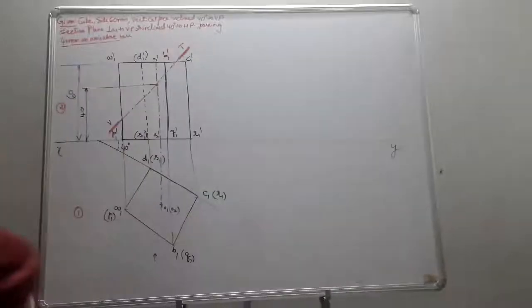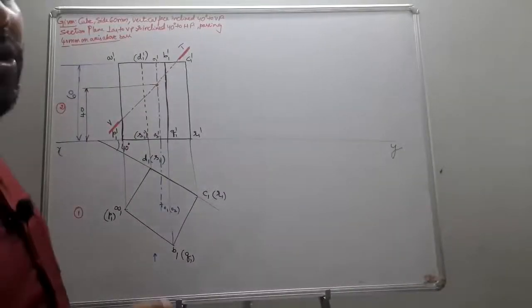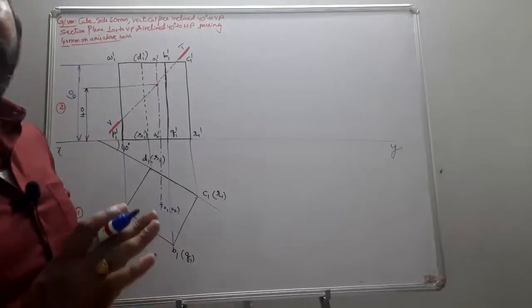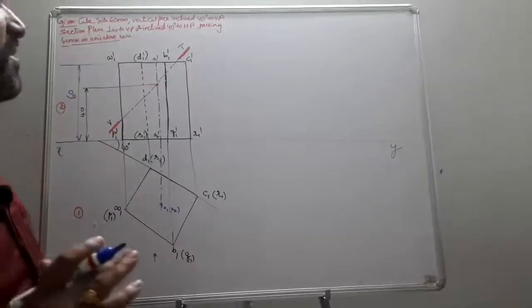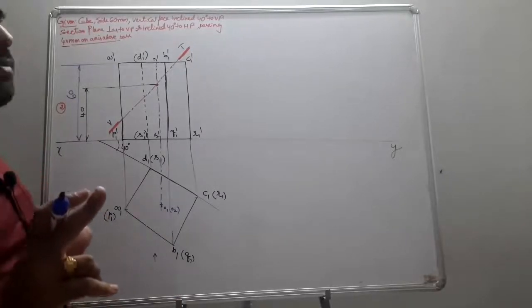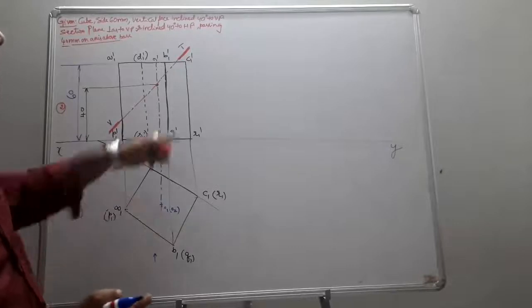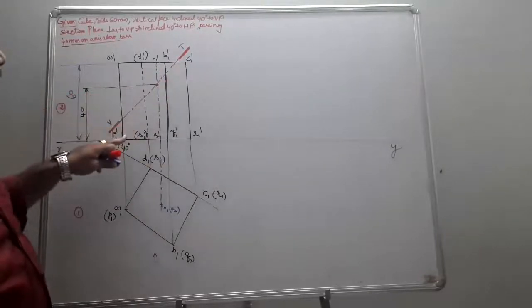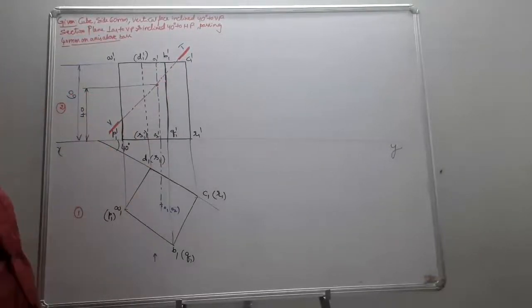Give numbering by taking the preferential order of the solid line first, and then we go for the dotted line, and there should be no number given for the axis line. So whenever your solid is going to be cut by the section plane on the top base or bottom base, you are going to obtain 2 points. Let us see.